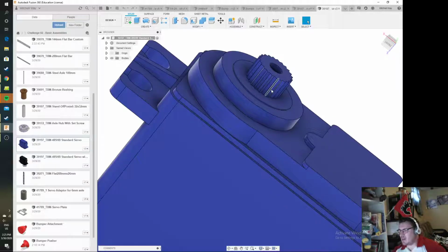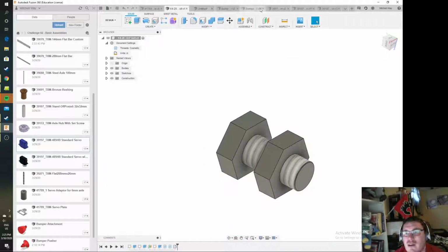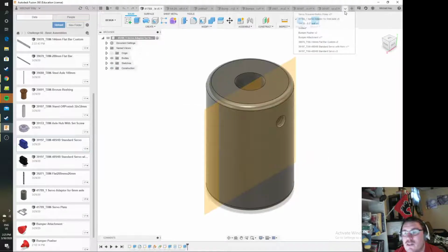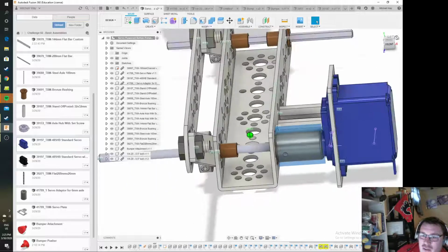You're prone to bending it. It doesn't like those kinds of lateral torsion forces on it that are going to bend things off of it, and that's often where we find servos that get completely butchered in robotics competition. So it's really a good idea when you're building it to actually go out, and I have lost my bumper system here. I have too many things open clearly. There we go. Okay. It is actually a really good idea for you to do what I've done here.